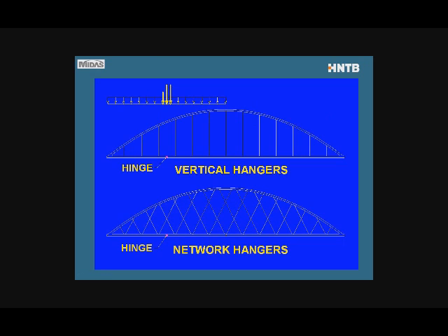And I will compare these 2 systems under this loading combination that's indicated in the upper left corner. So this represents live load over half the span. So there's some lane load and some truck load. And the crucial part of this is that it's only a partial load, which structural engineers among you know, arches are very, very efficient under uniform load, but they kind of fall apart under partial live load and pick up large bending moments.